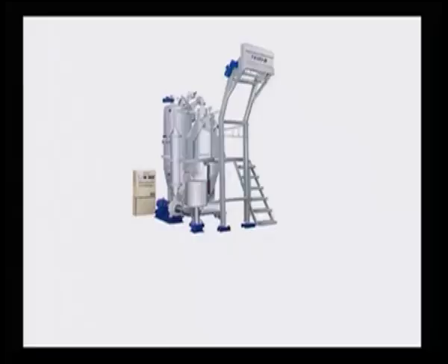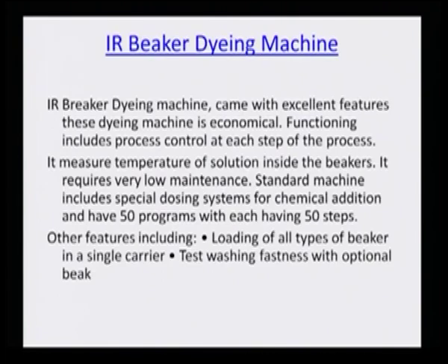There are nozzles to bring the dye solution onto the fabric, and the fabric is moving at a very fast speed. This is how the machine looks like. Everything is made out of a very specialized material, and the speed at which the fabric moves is very fast, and at no position the welded position is exposed to the fabric, because at the point of welding there could be some rusting that may occur and may get transferred to the fabric.